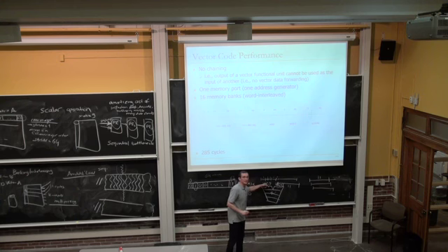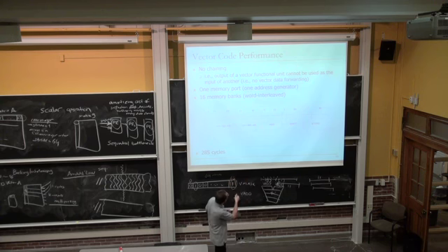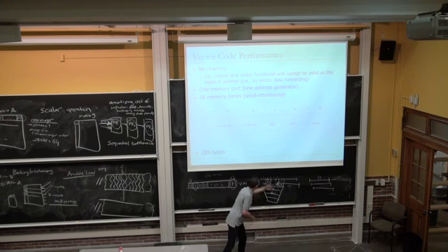In the next cycle, you can do the addition of the second elements, element 1 of each vector. Make sense? That's why you do the addition for the first element, and you get the result at the end of the 4th cycle here. And then you get the result out of the adder for every consecutive element.